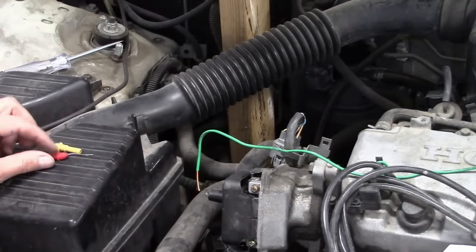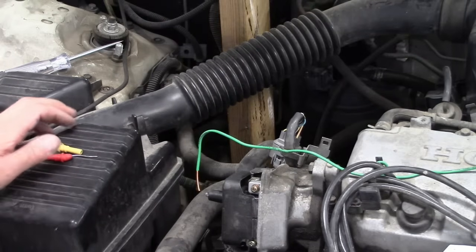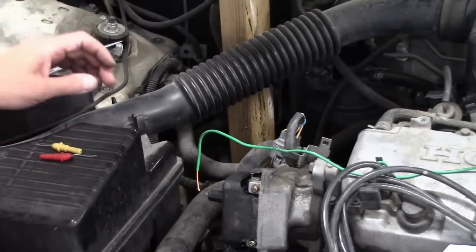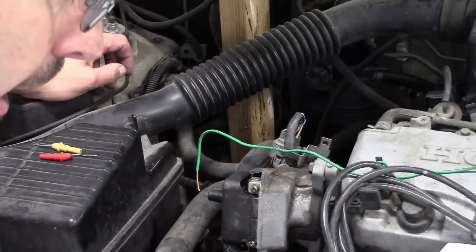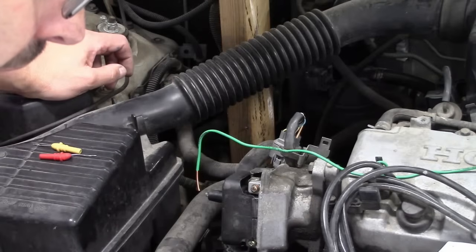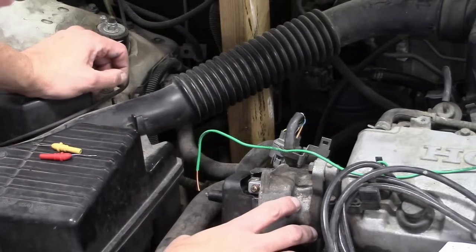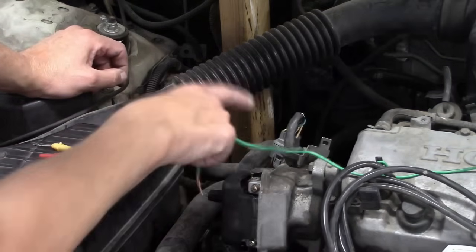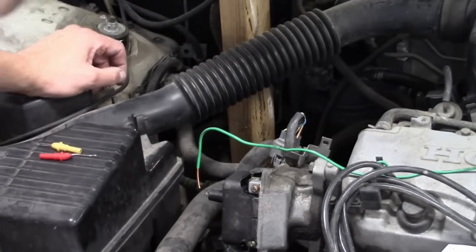So what I wanted to do was just go right to a confirmation on this coil, jump a spark from the coil's good. Unfortunately, it doesn't look like I'm going to have that much simplicity with that. So what I have to do now is either take this apart, or I could easily rule out everything else except the coil. That would be an easier way of doing it.